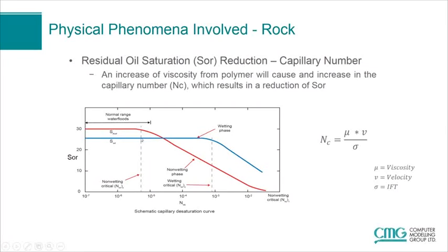So your reservoir flow may be somewhere around here, and then as you increase the viscosity, you'll move down this curve somewhat. Obviously you're not going to move down as far as you might with alkali injection or ASP, where the interfacial tension becomes very, very low. I mean, with ASP, you'll move way down here, very close to zero residual oil saturation. For polymer, you'll be up further on the curve here, so there'll be some small decrease, but as I said, not as much as with ASP.